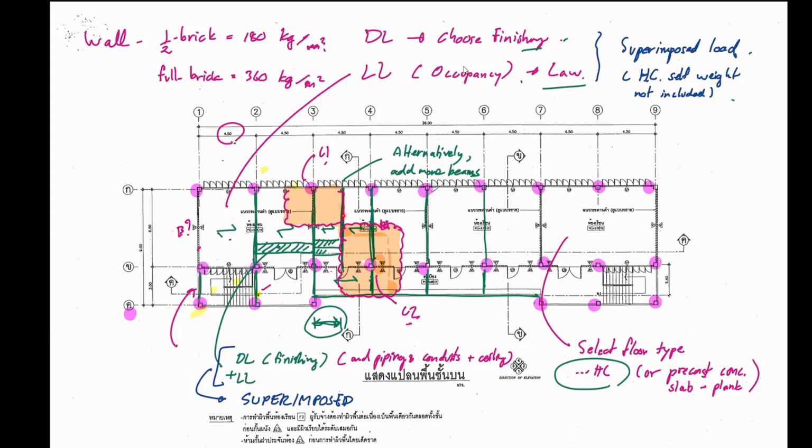But if you extend this, the first choice is just to use this beam to support it. But this is a steel structure, so the construction at this point may be difficult. So you have another choice to extend this beam from right here without having the beam to support this beam here. We can also do that, but this beam will in turn become a heavy burden to this point, and therefore you're going to suffer here. Okay. I see. So, okay, let's go to another question.